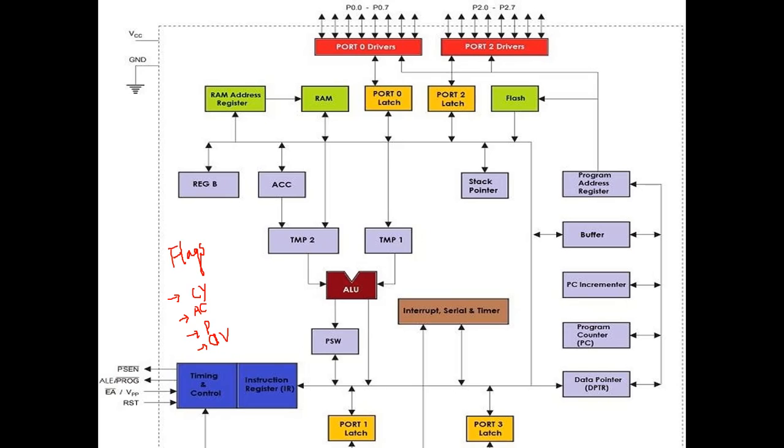Yes, we'll discuss in detail the flag register and the functionality of each and every bit in later sessions. Next, the two blocks in dark blue color are timing and control. In general, it is an oscillator circuit. An external oscillator provides the clock signal required for the controller to perform all the set of operations. Basically, the clock signal will be generated like this: the external oscillator signal is divided by 12, which gives the particular frequency required for microcontrollers or microprocessors.